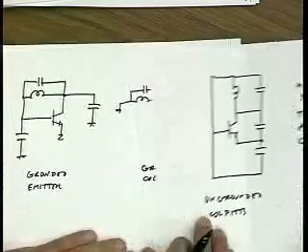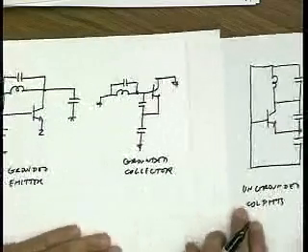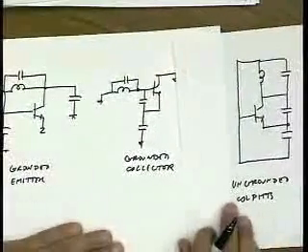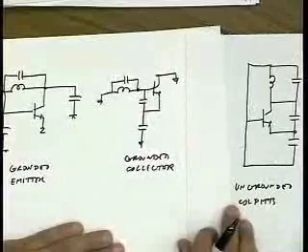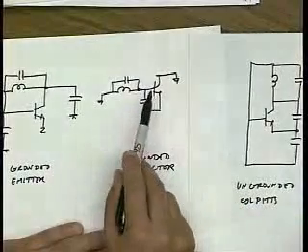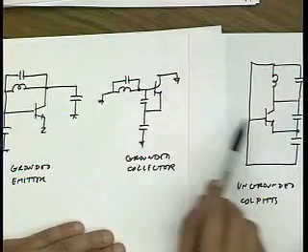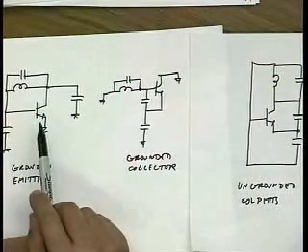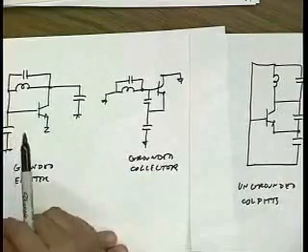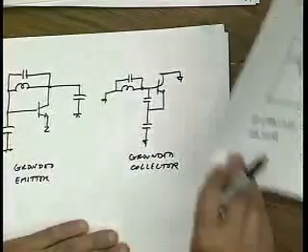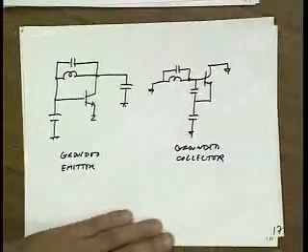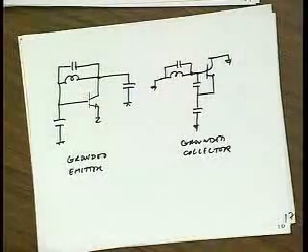And it's kind of cool because these oscillators at first seem to be very different devices, right? They seem to be very different beasts. One is an emitter follower acting like an amplifier. One's a common base amplifier. One's a common emitter amplifier. And yet they're all essentially the same oscillator. Okay? Questions? Yes? So they operate the same?